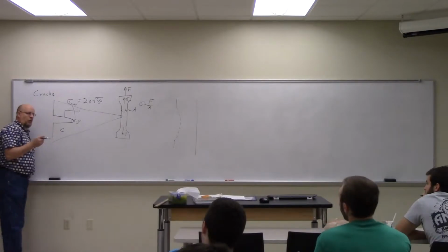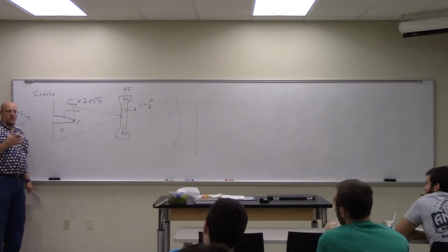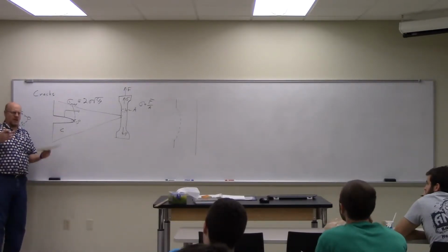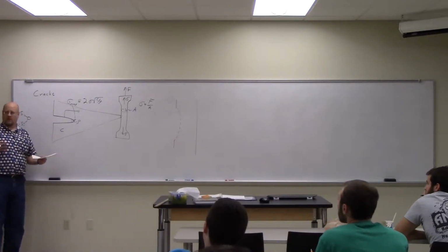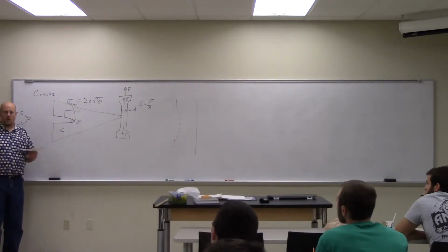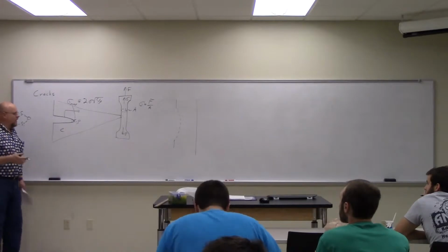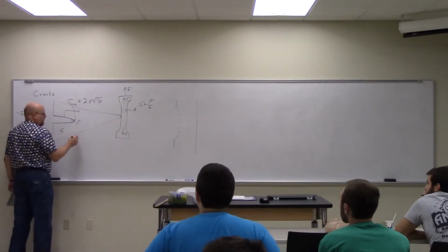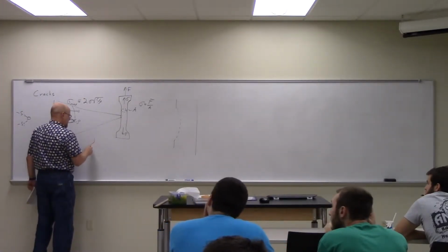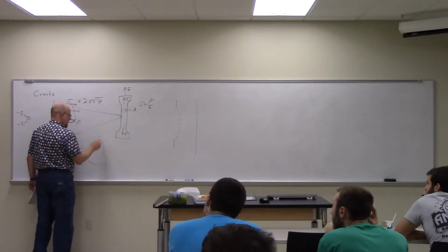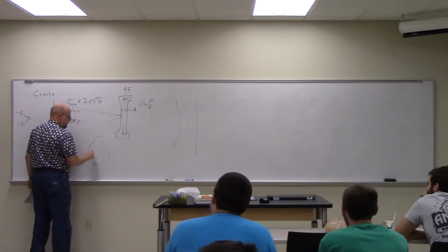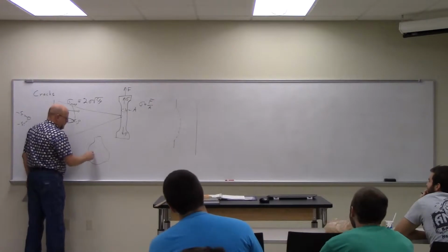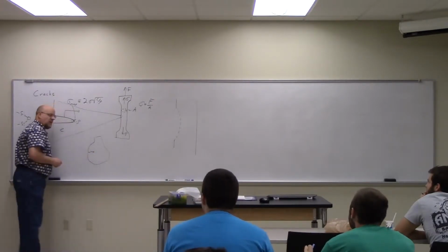So in cast iron stoves, if they would get a crack back in the day, because they get a lot of thermal stress from a wood fire or coal fire inside, especially in the wintertime, you can get cracks. So if you've got a cast iron stove, and this is just going to become a big potbelly stove here, I have no idea what it looks like, and there's a crack growing in from the side, they would drill a hole at the end of the crack.